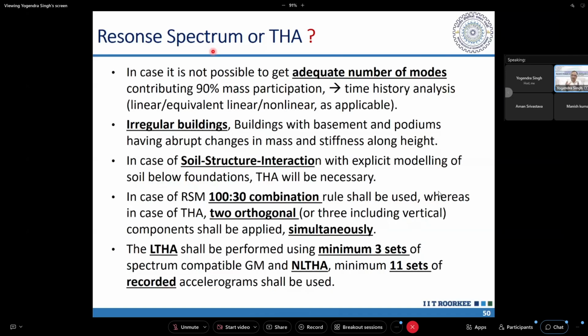The well being very rigid, it will not be accepted, and that will move more or less rigidly with the soil. So that's why on the well, I have to consider the additional forces, and those forces I can consider simply as m into z. So what I can do, I can make a model of the bridge by fixing the pier at the top of the well, and then the inertia force acting on the well, I can calculate separately, and that I can apply as a static force on the well. That's how I can design the well.